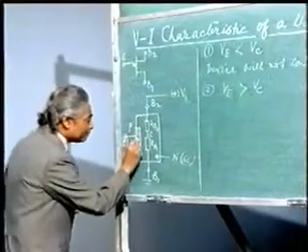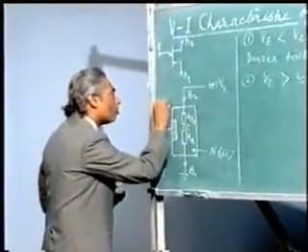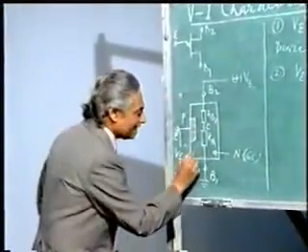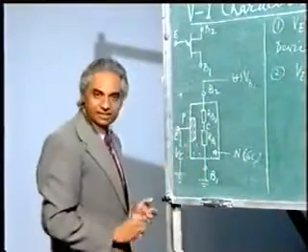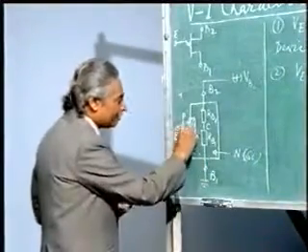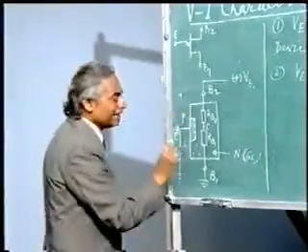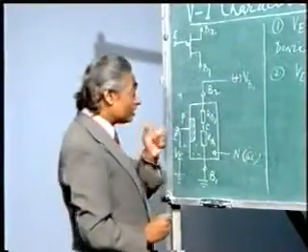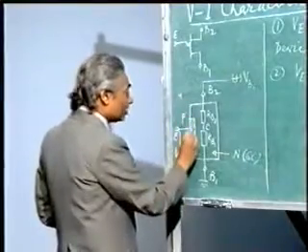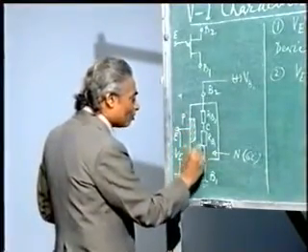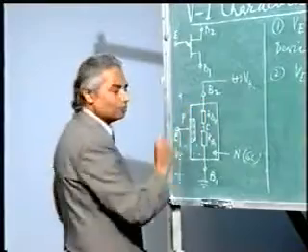In this p type of material you have positive holes as charge carriers, and here you have negative electrons as charge carriers. So these positive holes will drift inside and they will make positive hole negative electron pairs. Now there is a question, this positive hole coming out of this p layer may go to B1 or it may go to B2.